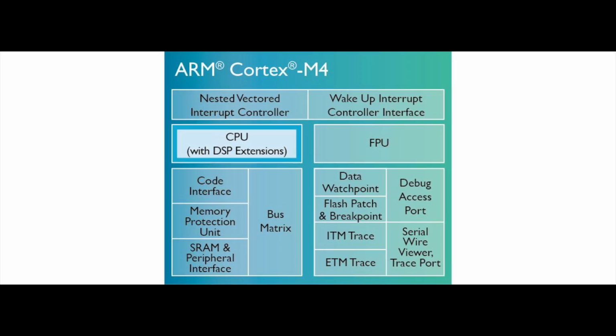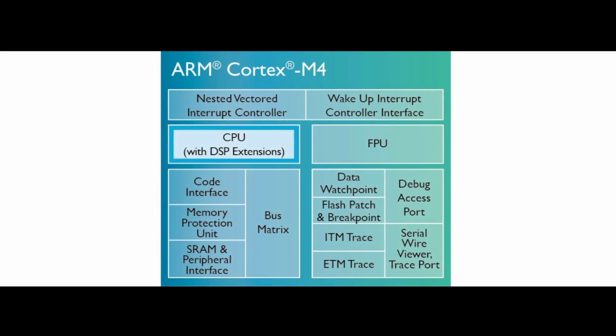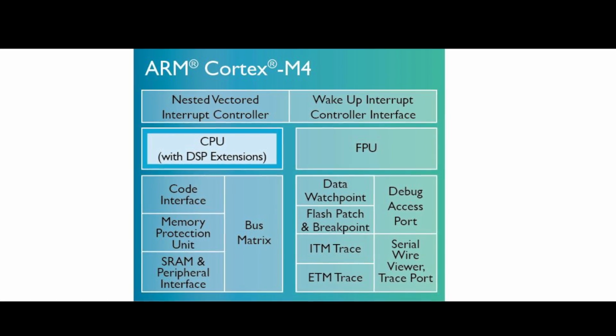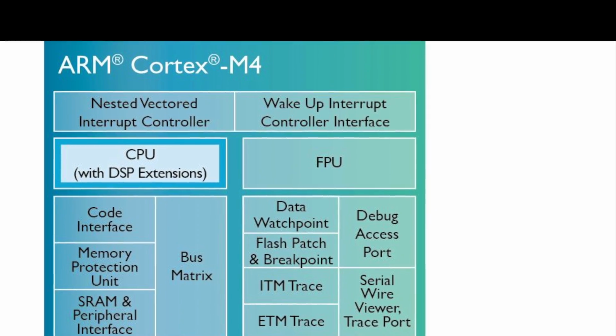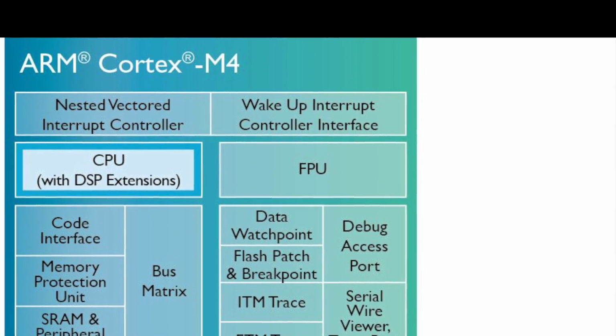Now, 32-bit chips won't necessarily have floating point operations built in, but some do. Like I think the Cortex M4s do have, they support floating point operations. But even if you don't have an FPU, if you have enough memory space and enough horsepower, you can still muscle your way through it a lot better and have plenty of headroom.